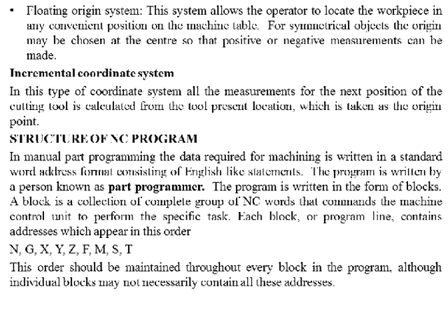The particular alphabet should be called in the same format, and this set of instructions will be written in the form of a block or a program line in the same format. Therefore, this order should be maintained whenever we write a block in a program. Although it may not be necessary for us to call all the addresses, each and every alphabet is called an address. It may not be necessary to call all the addresses, but the order should be maintained throughout every block in the program.